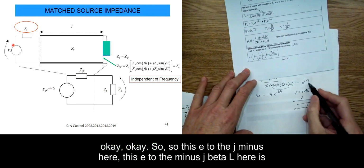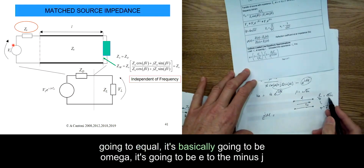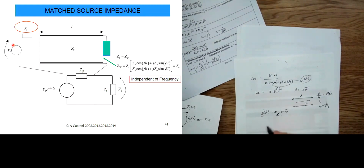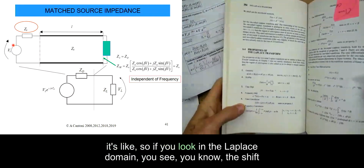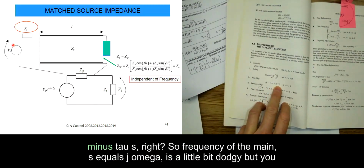So this e to the minus j beta L is going to be e to the minus j omega TD, the time delay. In the Laplace domain, this is effectively just a time delay: if you shift the function in time by tau, then in the Laplace domain it's F of s e to the minus tau s, right?